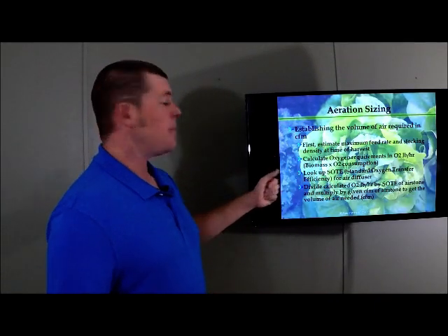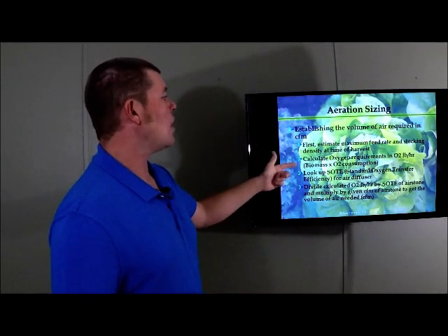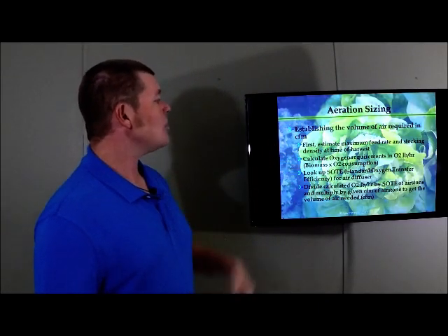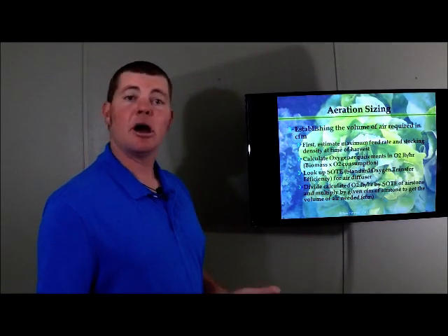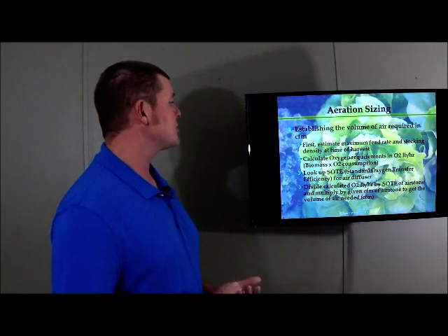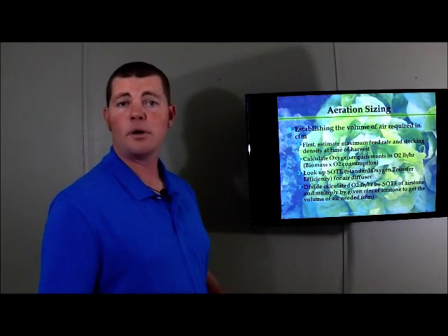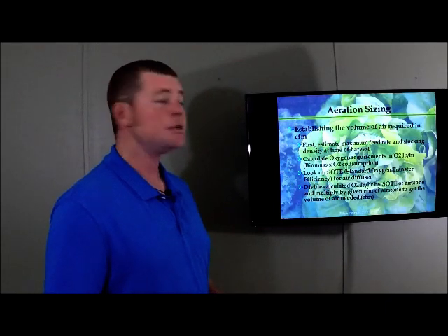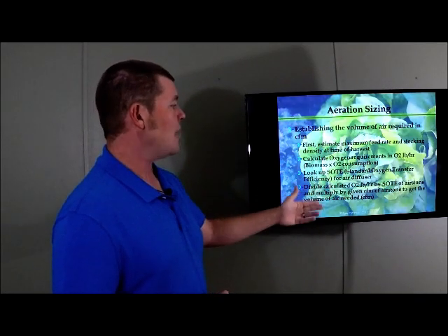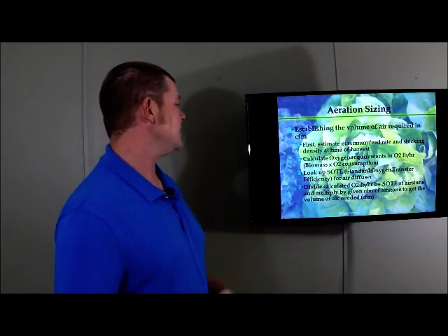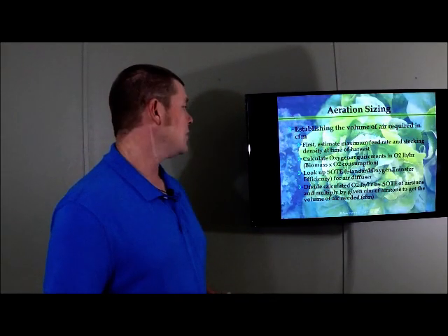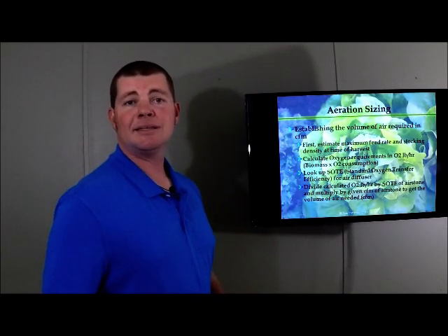So we do that by calculating the oxygen requirements in pounds per hour, which is biomass times the oxygen consumption of that biomass. We look up the SOTE, the standard oxygen transfer efficiency rating for the specific air stone that we're choosing to use, and then we divide the calculated oxygen in pounds per hour by the SOTE of the air stone and multiply it by the given CFM of the air stone to get the volume of air needed in CFM.